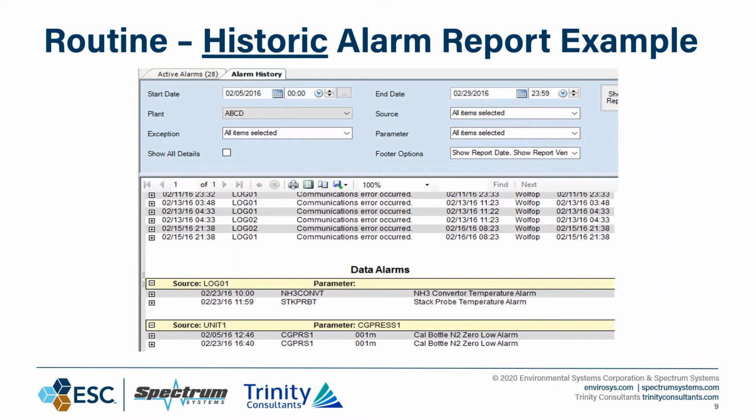It's a very valid statement. Particularly be on the lookout for nuisance alarms, those that just seem to pop up indiscriminately and just go away. Nuisance alarms are those kind of alarms that just get ignored. Hands down, they are the worst sort of problem where you just have an alarm pop in and go right back out. Something chattering in the system, a bit chattering in the system that is creating nothing but a nuisance record, should probably be investigated. We really want calm in this area.